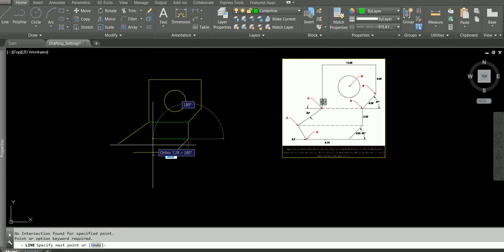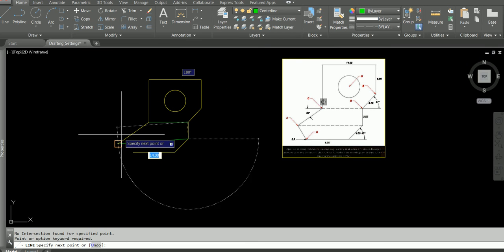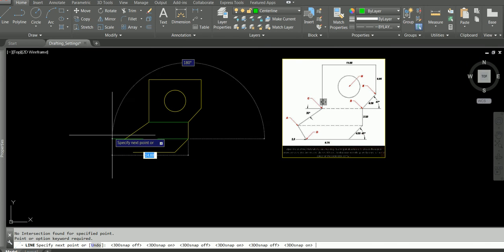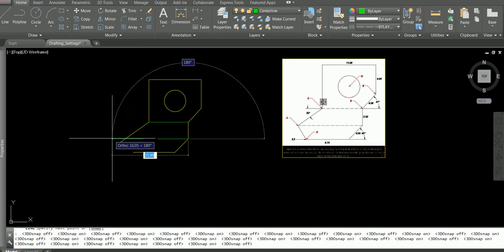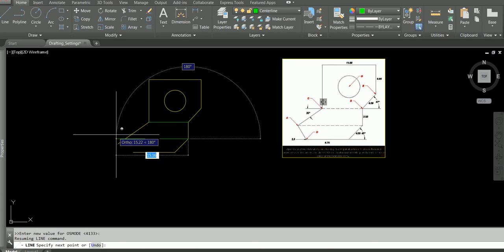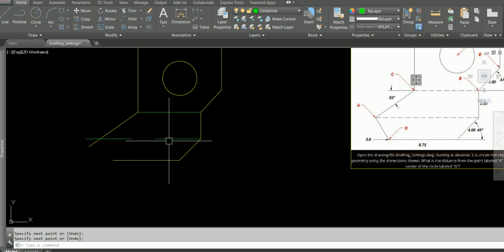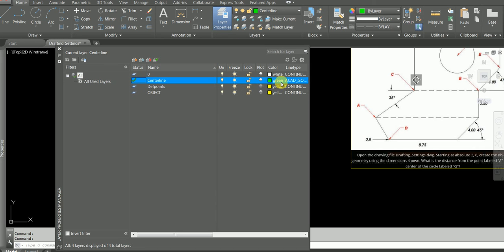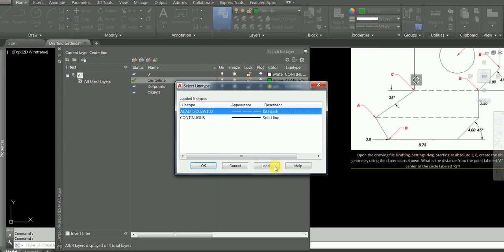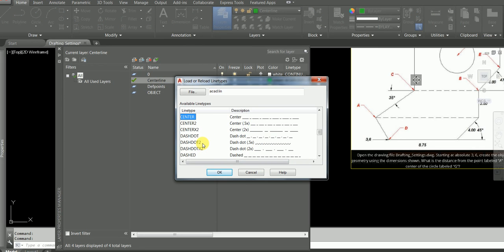I think the scale is giving me headache. I'll tell you one thing, press F3. Just keep pressing F3. I'm pressing F3 here. Just click here. Okay, see what's happening is because of the object style which I used here, line weight, I would say, come here, line type. Let's say load, we have something called a center line.